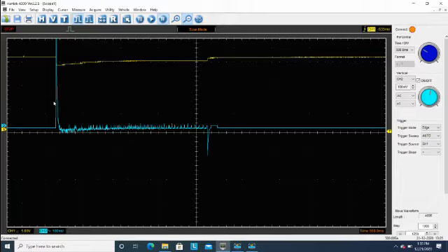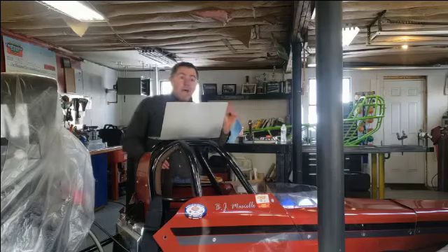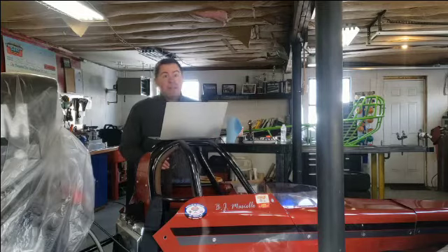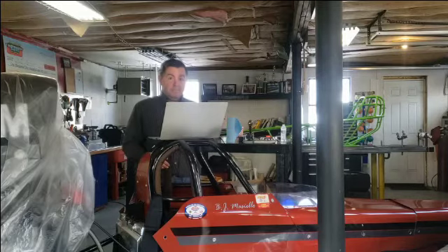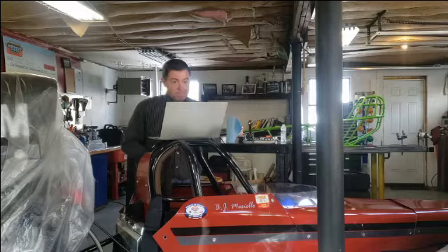When you increase the temperature of copper, its resistance goes up. Copper is what's called a PTC, or a positive temperature coefficient resistor. So as that wiring, and that includes the windings of my electric motor, heats up, its temperature increases, and therefore my resistance increases slightly. Part of the reason we see this drop in current taking place.